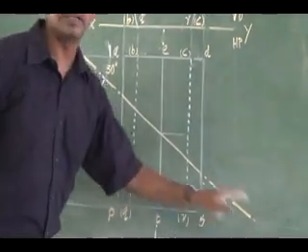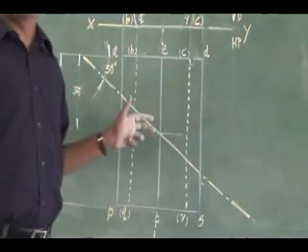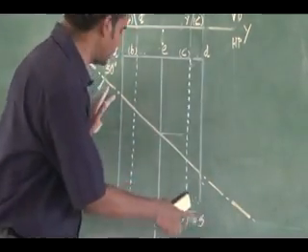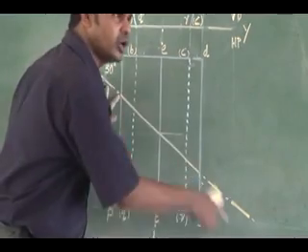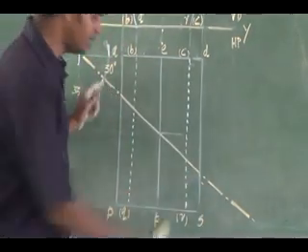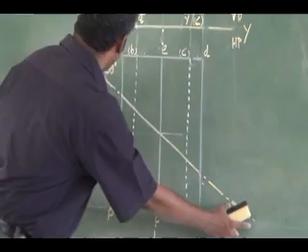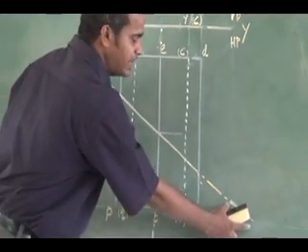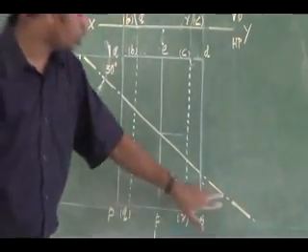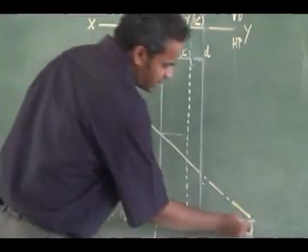Then the cutting plane is 30 degree inclined, I have represented. The cutting plane you neatly represent. All through the solid you have to show it as a visible continuous line, then extend outside at the ends. Both ends of the axis line have to be thickened, in two lines.